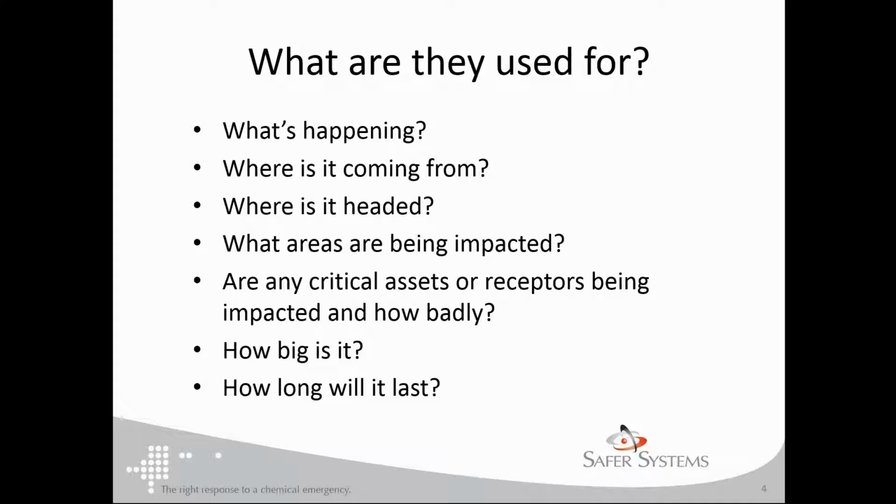By doing that, you're changing the paradigm of the monitoring so that you're getting a constant feedback loop from the incident and from the plume and feeding it back into incident command to get a full operating picture of what's actually happening. And when you take this one step further, you can actually use the live data in the dispersion model to calculate the size of a release, changing the model from an estimate to a live measurement.